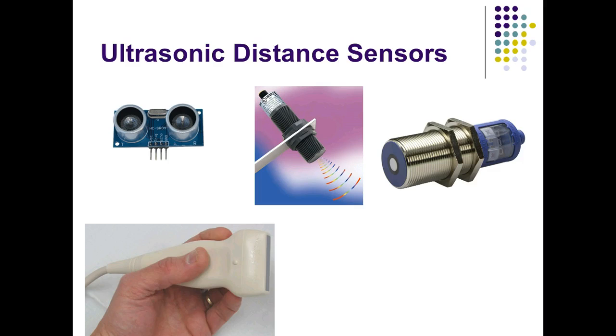We either turn something on or we turn something off, right? You understand? So with a digital ultrasonic sensor, the A to D converter would be built into it. It can be easily done because it's electronic anyway, right? So we have to apply power to it. The one we have over on the Amatrol line gives us the ability to set what we call a span, which is two digital reference points. So we put those blocks through there. If the block is not the right size, it's going to reject it.